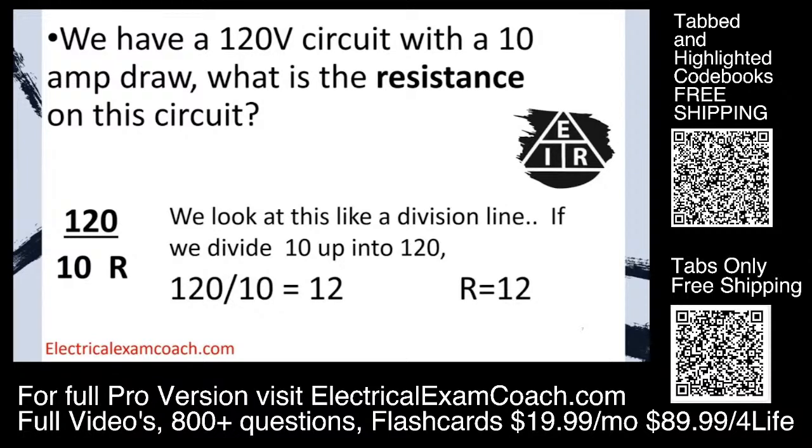Then all I have to do is divide. I divide 120 by 10, and it lets me know that there should be 12 ohms of resistance on this circuit, meaning I should be able to put my amp clamp out and read 10. I should be able to put my voltmeter out and read 120. And I should also be able to measure the resistance and measure 12 ohms.